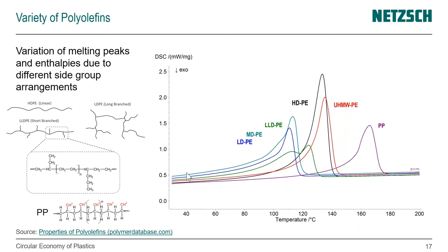And then how can we check for other types of contamination which may be found in the waste plastic? Ideally you have at least an idea what you're dealing with. For example, if you think of metal and other contaminations, I actually think that thermogravimetric analysis is better, because it's a method that we frequently use and that is set up to measure to very high temperatures and get all degradation effects that happen in this temperature range.